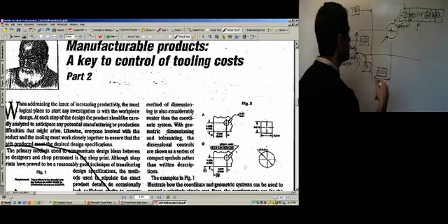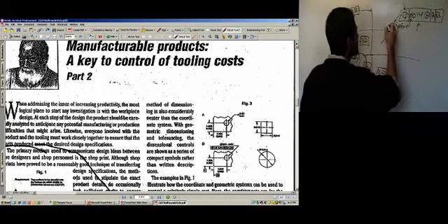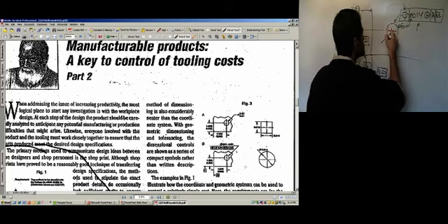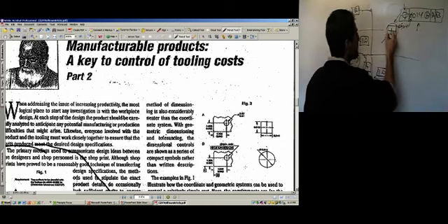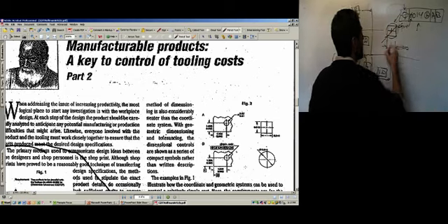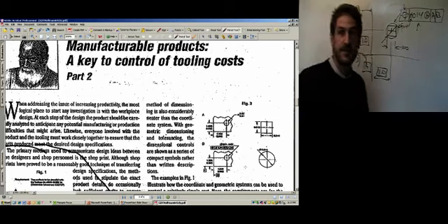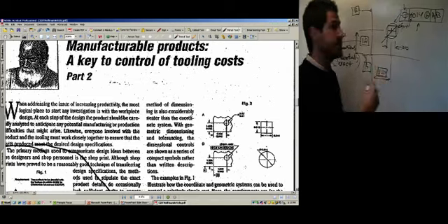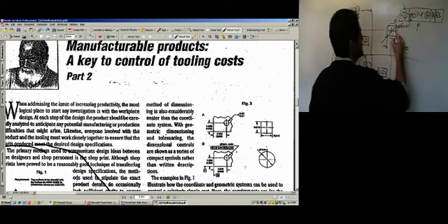If we looked at the other way to dimension this, it gave us basically a square tolerance zone with sides that were 5 and 5, or basically 10, and it would also be 14 on the diagonal. So on the diagonal, it's the same. But if we dimension it with GD&T, we get all this extra area.